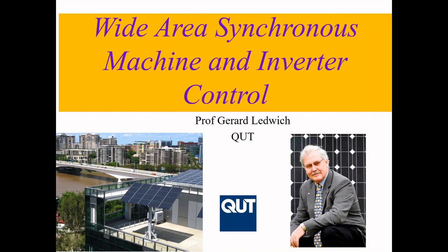Okay, so if there was a very big solar farm connected into a weak area of the Queensland grid, then its phase lock loop will have problems injecting at the right angle without its own variations causing synchronization problems. Now, if we broadcast the angle of Central Queensland to all inverters in Central Queensland, there's no possibility of oscillations, and the issue then is to make sure that our voltage profiles are maintained and that we can transfer the required power levels. So this process of weak grids is mainly a problem for stability of phase lock loops.